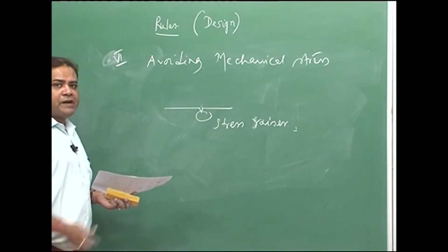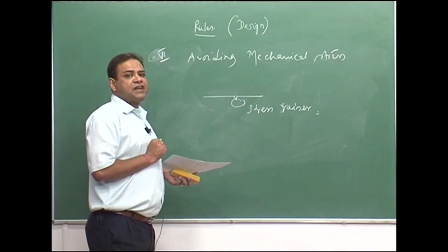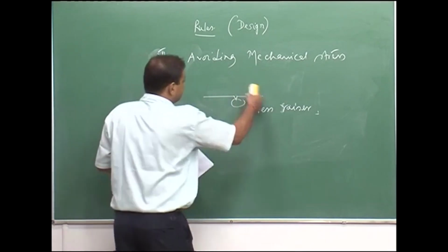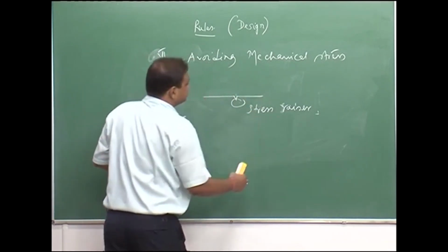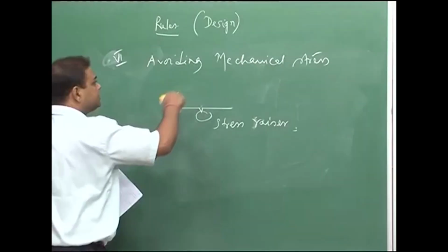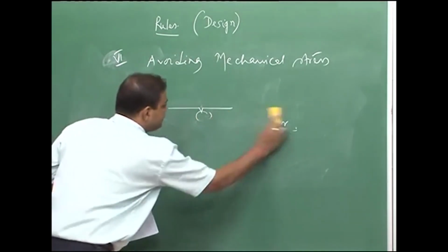For example, for an impeller blade, if that blade is very smooth, then cavitation damage can be avoided to a great extent. In that case, stress raisers or those sorts of dents are not good; they can add to the corrosion process that is going on.